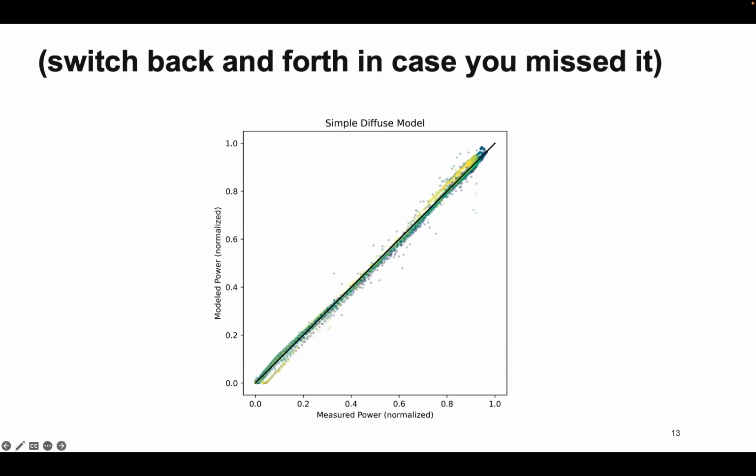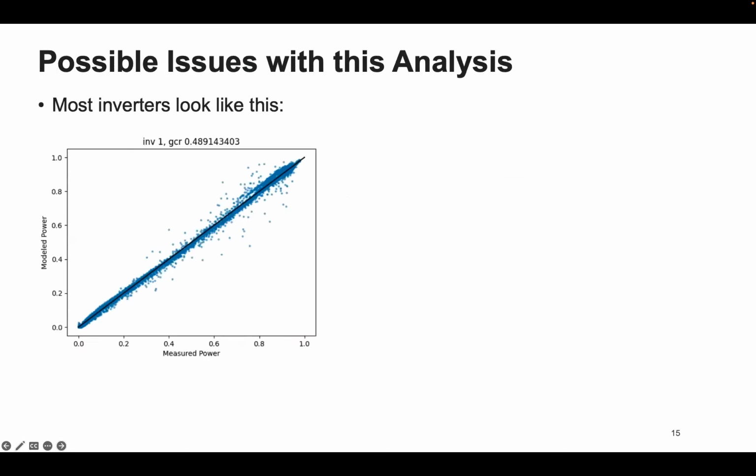Big caveat: the site's more or less in the desert, so 20% diffuse irradiance seems to work pretty well. Clear skies almost all of the time. There's a little bit of overcast in our data set, but not very significant. So those are two main conclusions. Inverter level models help maybe a tiny bit. Decomposition, the way we did it, does not appear to help.